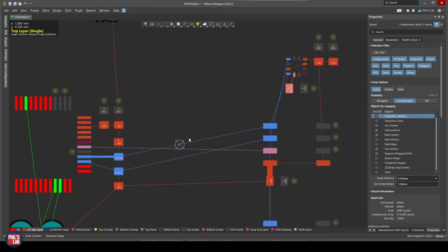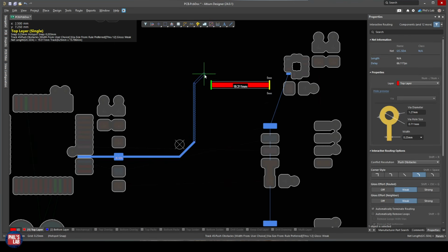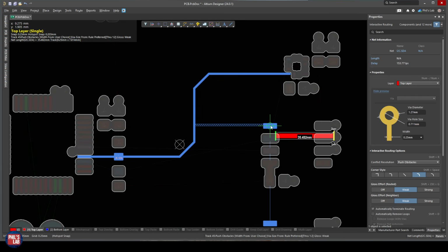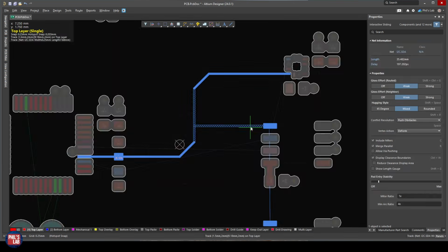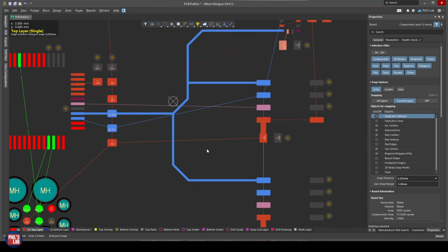From there, I have a couple options with this SDA. What I could do is this kind of branch routing. So if I just route up to the top SDA of the magnetometer, I can branch off and route, for example, into one of the EEPROM SDAs. I could branch off below and into the bottom EEPROM like so. And typically, for higher speed interfaces and buses, I wouldn't really recommend this branch topology, but honestly for I2C, especially for these kind of short trace lengths, it really doesn't matter very much.